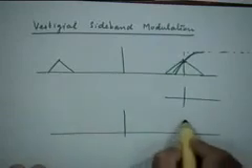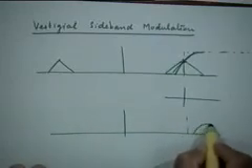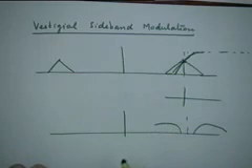For example, for speech signals, we know that the low frequency content is not that high. I discussed with you at the beginning of this course that a speech signal has significant content from, let's say, 300 hertz onwards. It practically has no content between 0 to 300 hertz. So in that kind of signal, the spectrum after frequency translation would perhaps look like that.